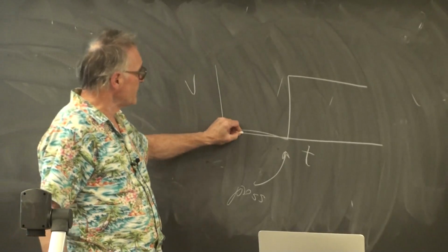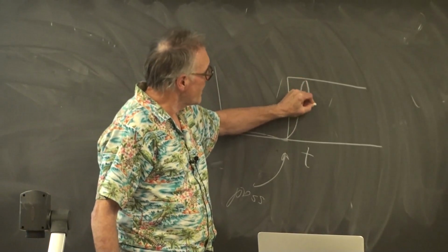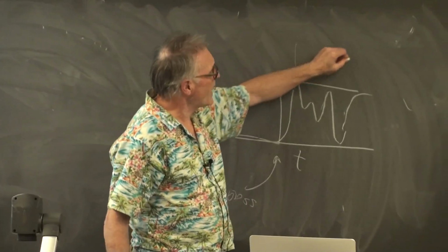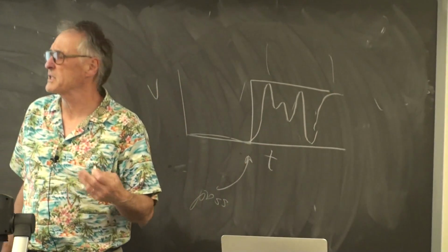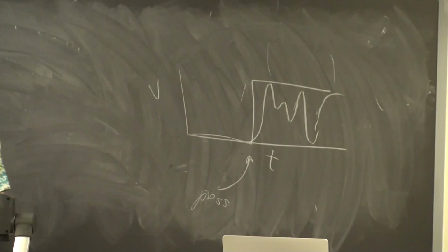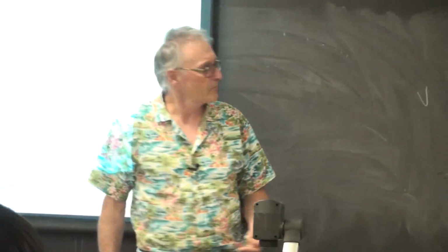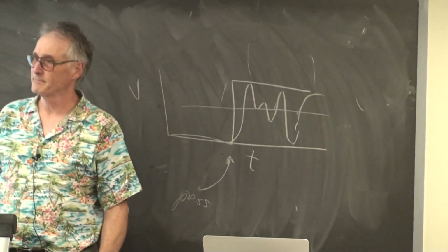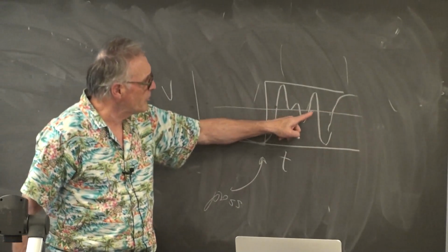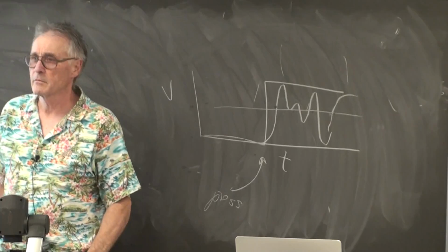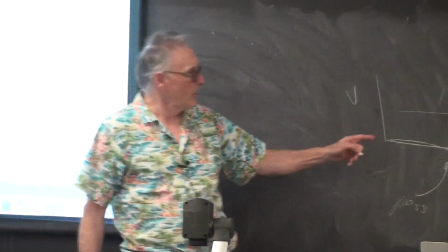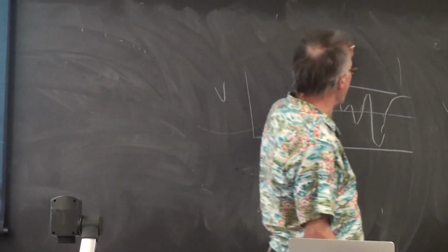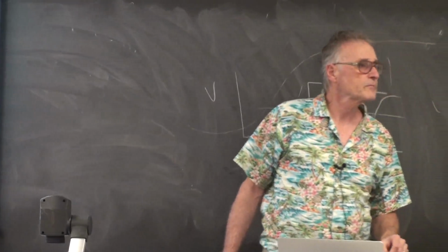And what you actually get is something that looks like this, with a characteristic time of perhaps 5 milliseconds or 10 milliseconds. The button bounces. CMOS threshold is here. How many times did you push the button? 1, 2, 3, 4 times, says the computer. Even though the human, who's thinking on a time scale that looks like this, says I pushed it once.